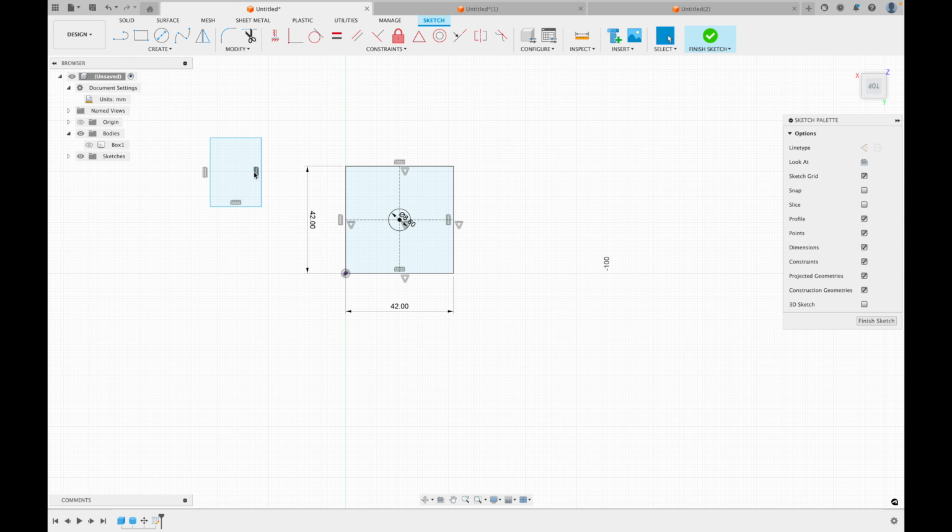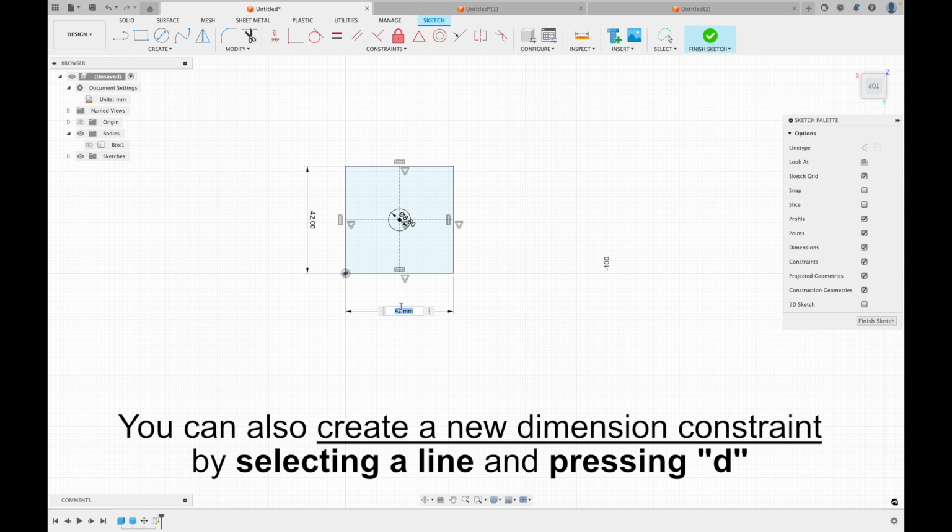So if I deleted these constraints, this shape is completely unconstrained, and now I should be able to just move it like so. There is actually this constraint as well, which connects these 2 points together. So when you're designing your objects in Fusion 360, and you're making sketches, it's best practice to keep your design fully constrained like this, because let's say we want to change dimensions of that, you can easily change it in the future, and it's just one of the coolest features of Fusion 360.